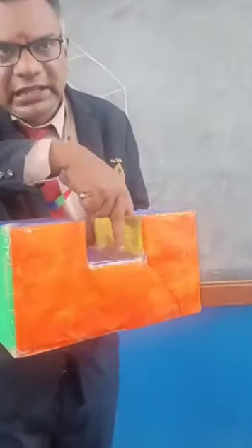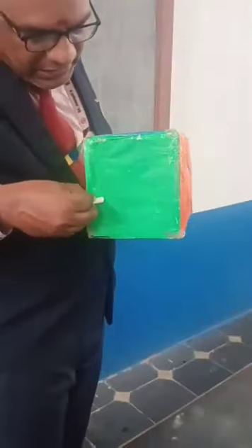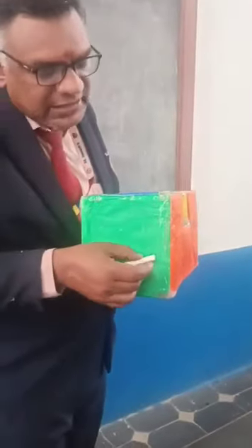But when you are viewing from front view, there is a slot there. But when you are viewing from the side view, there is a slot there, but it is not visible. So it is the same projection. For side view, you have to make a dotted line, so it is called a hidden line. So this is the side view.